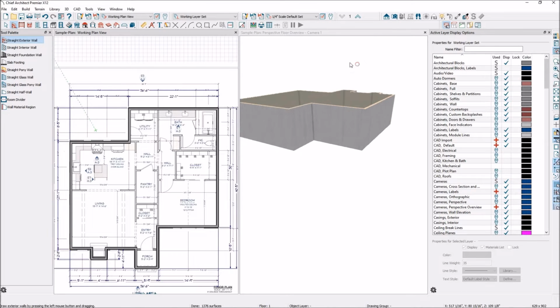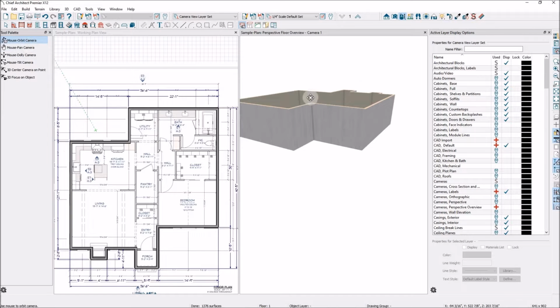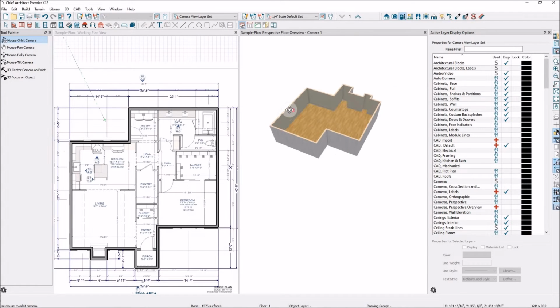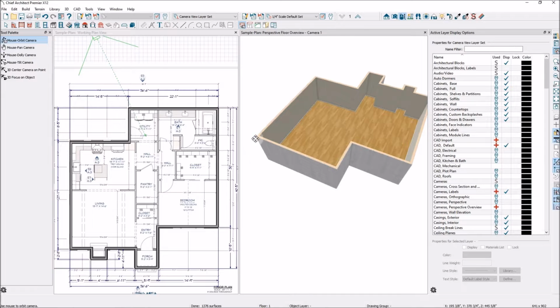And that all connected. If I go over here, you can see that once I connected all of the exterior walls, it created a room inside. It generated the floor and the baseboards and everything that I've got set as my parameters, which we'll get into. It also generated the ceiling for me, but you can't see that because we've got this view with it cut off. Once you get everything connected, it creates the room.